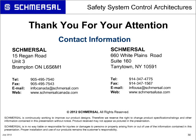What guidance is provided during the evaluation phase on what level is necessary for the task? Some people may want a Category 4, but do not realize what they are actually asking for. We could be causing design problems when the probability of an event is low? Your last part of your statement is 100% correct. What happens is somebody will make a bold statement, it's got to be control category 4 without doing any evaluation to it. Well, that's the safe way of doing it.